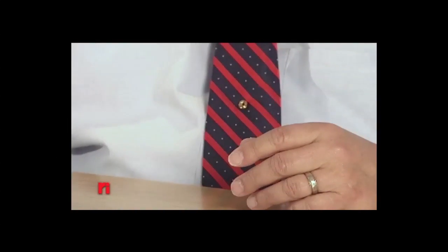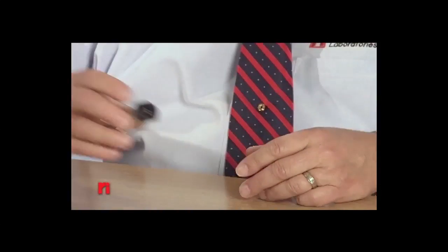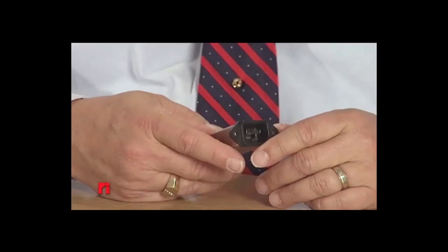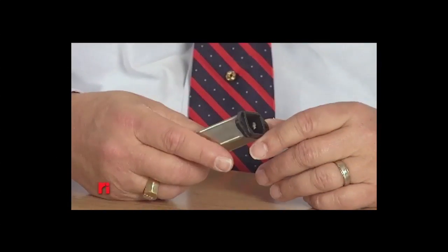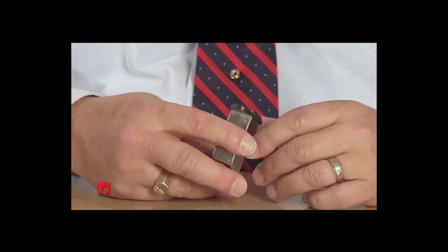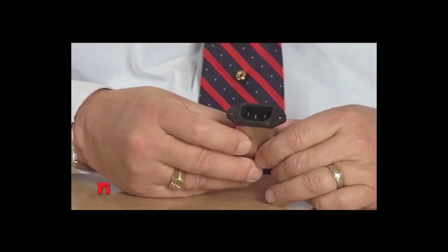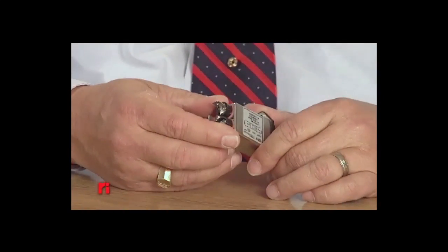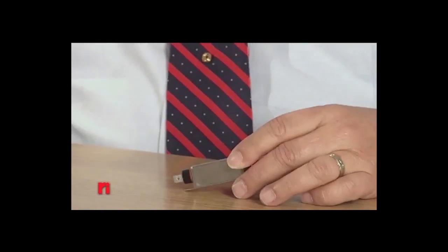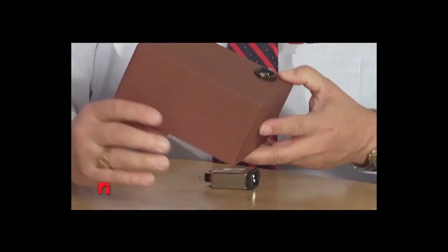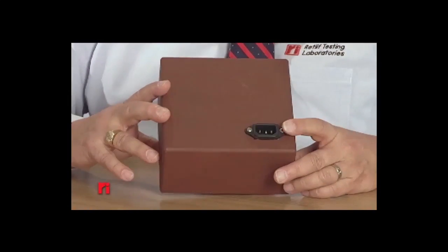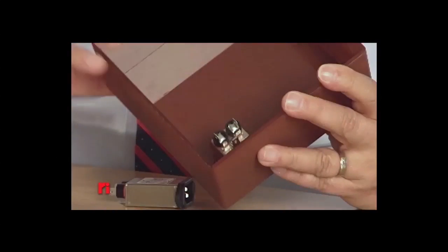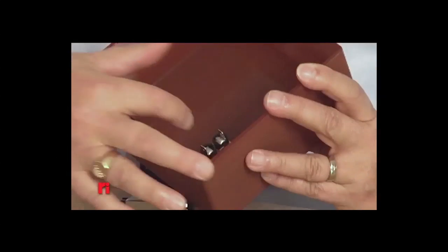The last filter that I wanted to show you, you're probably familiar with, not even aware that you see it many times. It's a commercial grade input power line filter that's used in many computer operations. When you're looking at the back of your computer, you're only seeing this. You're not seeing the back, which is actually the RF filter. And I have created a little mock-up here to show you how that would appear in a piece of equipment. You would see this, but actually that cabinet is providing a shield between the input and the output of the filter.